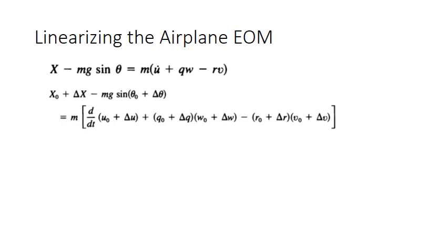Using the pre-mentioned symmetry assumption and aligning the body x-axis with the velocity vector, we will nullify these variables in the x-force equation.